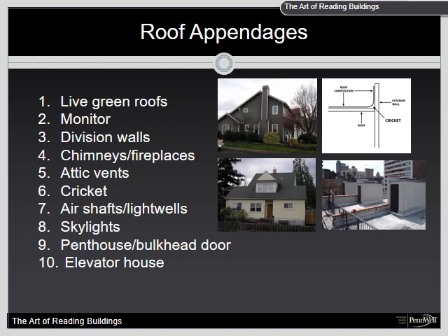Although this configuration delivers acceptable sealing, it also provides an excellent avenue for the extension of fire. When this condition is suspected, the cricket must be opened and exposed. Okay, so essentially this is a void space for the roof. And it's that little corner between the horizontal and vertical members of your roof.